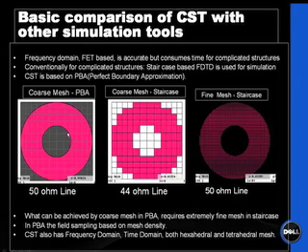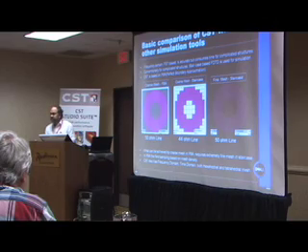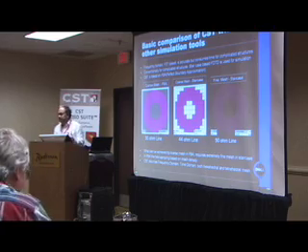So what happens is, when you account for those mesh cells too, even a coarse mesh will give as accurate a simulation parameter as the fine case in the case of staircase mesh. So this is what I felt was very advantageous with CST, that is, your accuracy is not lost just because you're going fast.